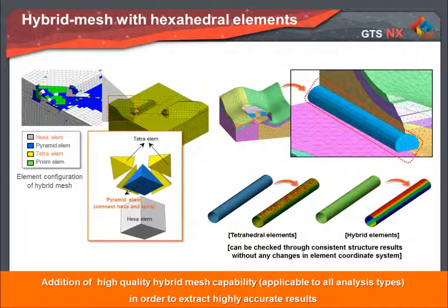between the two. The main advantage of using hexahedron elements is that they provide comparatively more accurate stress results than tetrahedral elements, and the advantage of using tetrahedral elements is that they are more effective for modeling sharp curves and corners of complex geometries. GTS NX is capable of utilizing both tetrahedral and hexahedral elements without any significant loss in modeling or analysis speeds.